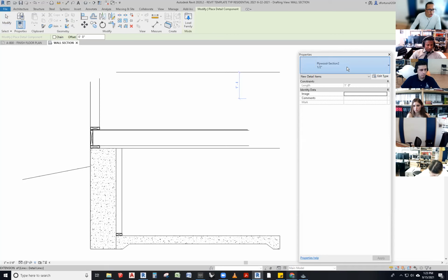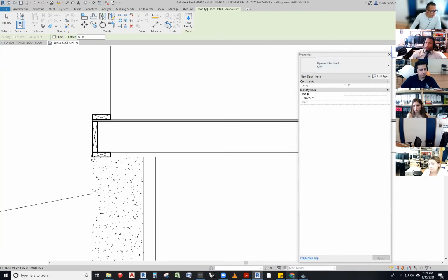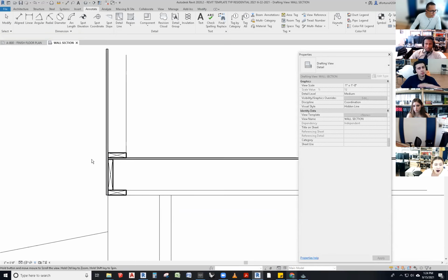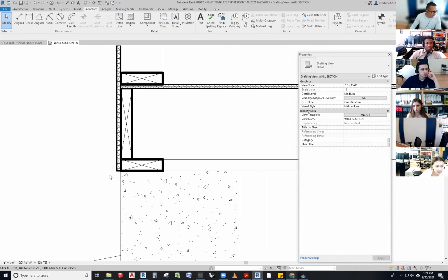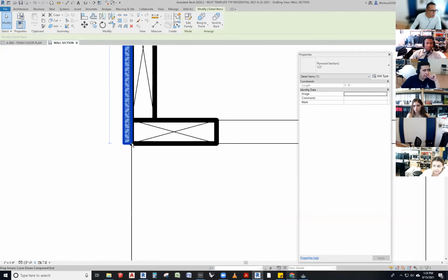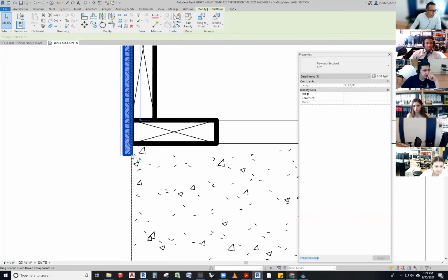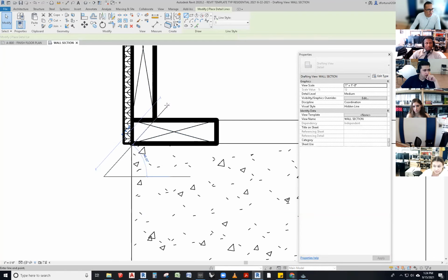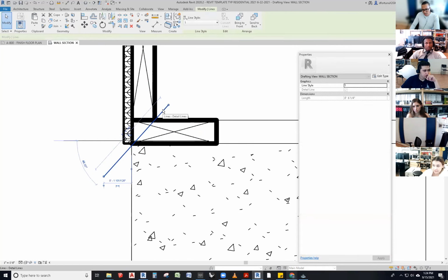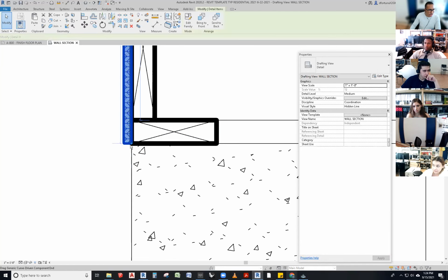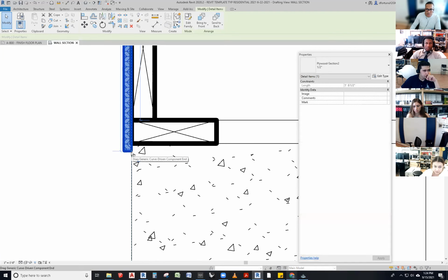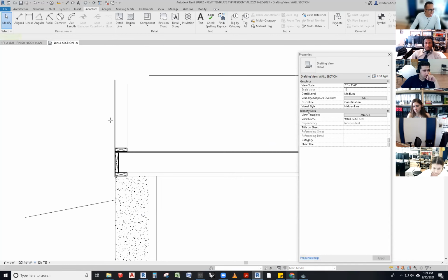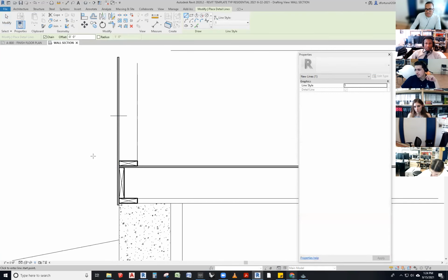We're going to put our exterior sheeting, which may be made out of plywood, and we use a zip system that does not require something called an air and vapor barrier. That's detailed. We'll explain that later. I always want you to overlap this. Why? Because if you don't, water still has a chance of going through there and breaking your foundation and leaking in there. Overlap it by at least 1/2 inch or 1 inch or so. Okay, so these basically get attached to your studs.